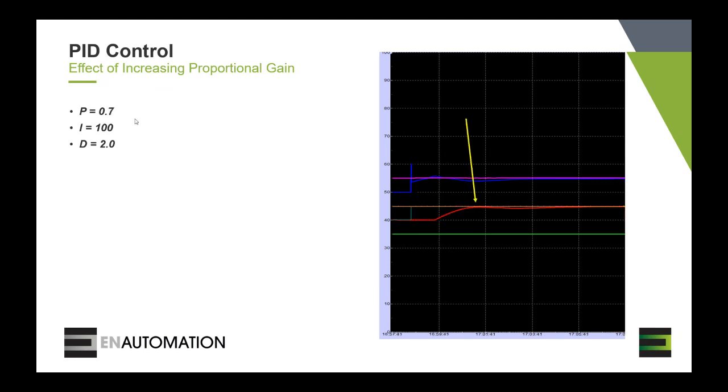And we reach a point where we're getting close to the critical scenario, critically damped scenario. We're starting to see this first overshoot and a slight undershoot. So we are getting close to the ideal response of the PID controller.